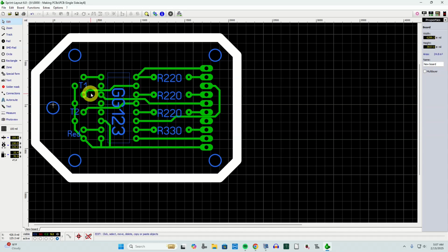It's easy to route them, but to make sure everything is small enough that it still conducts electricity and that your process can make it to that size. Over here, we've got a couple of transistors and then an LED over here. These 5 items are mounting holes, and they would be 1/8 inch diameter. They're actually a pad that I create on the top surface. We'll get started by creating our IC chip.